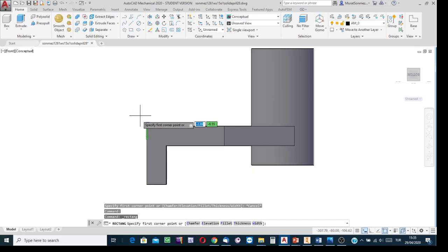I'm going to write the coordinates, of course, relative to the origin. The first point is located relative to the origin, but for the second point and the following points, I input the coordinates relative to the precedingly marked point. Okay, for the first corner, the x, y values.